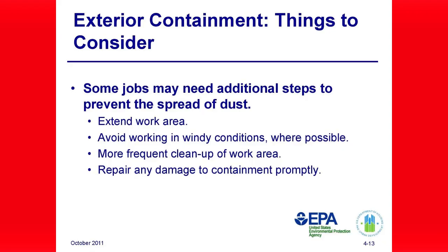A dust cone opens up the higher you are. So if your work area is 20-30 feet up, the dust cone at the bottom is much larger than possibly the 10 feet of plastic that you have placed. It is your responsibility to account for these things. EPA provides you a minimum of 10 feet of plastic sheathing requirement from the edges of the work area, but the cone might not be enough, so you have to go beyond that. Extend the work area. The simplest solution is to extend the ground coverage with plastic sheathing beyond that.